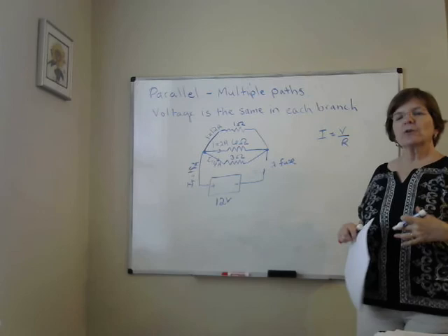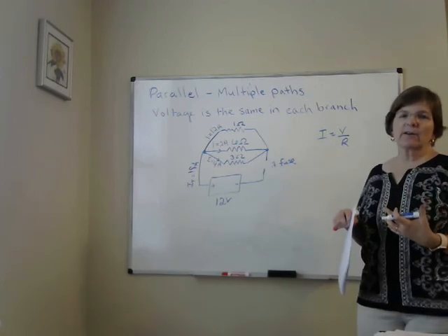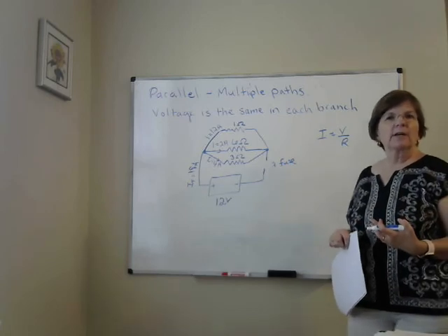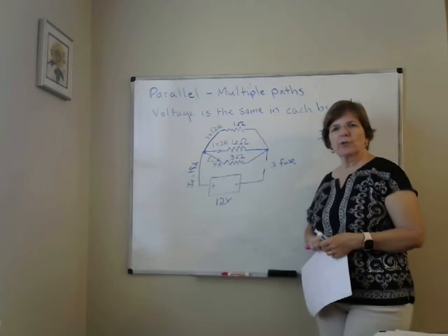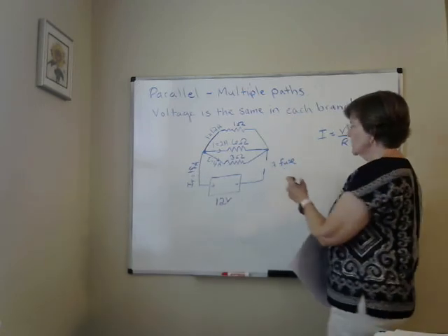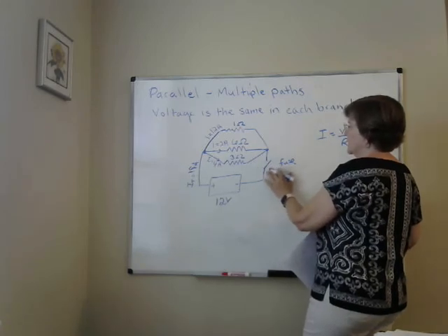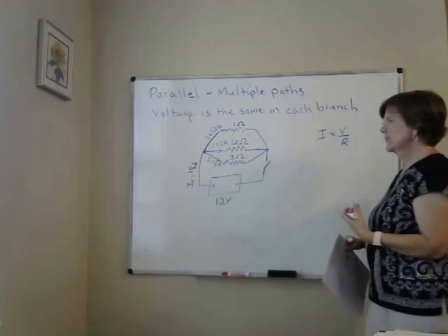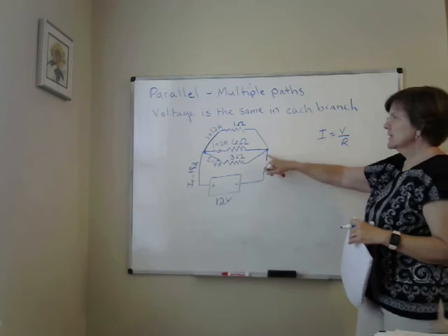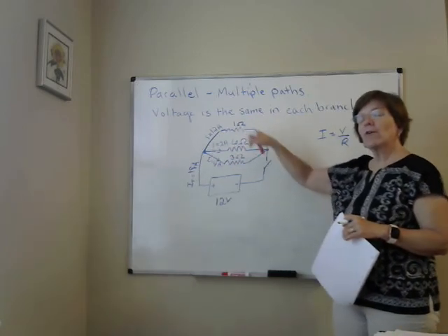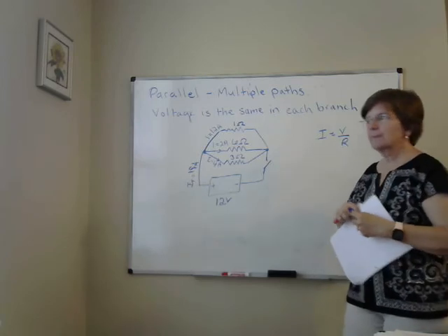You want to avoid too high of current because too much current can cause the wiring to overheat and catch your house on fire. We don't really use fuses so much in our homes. Now we use circuit breakers. Circuit breakers are more like a switch. And that switch will pop open. If it's a 15 amp circuit breaker, it's going to pop open anytime the current goes over 15 amps. So when you turn on this thing that drew 12 more amps of current, it's going to pop open to try to keep your home safe.